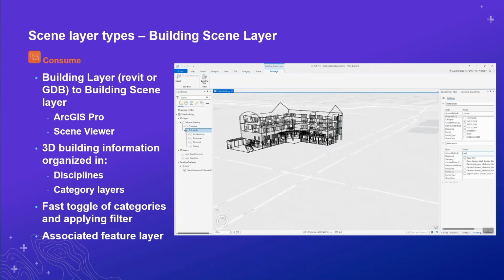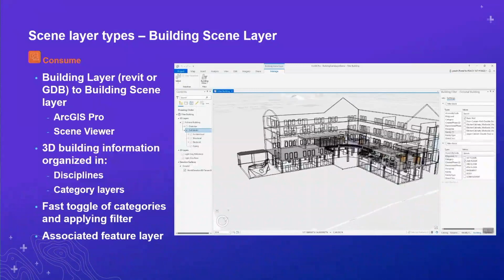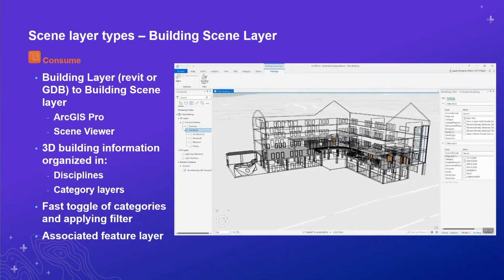For example, right now, the inner walls, even though they are part of the family basic walls, draw as solid. If I change the second filter block to be on top, the inner wall will be in wireframe because the filter block has priority.